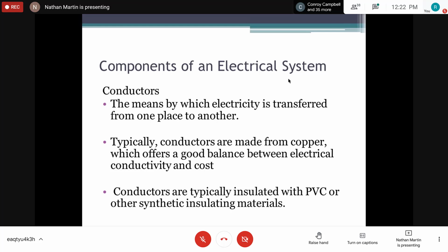Now, the different types of cables that we might use for the incoming electrical service. So remember, we talk about the entrance, we talk about within the building and so forth. We talk about the triplex wire, right? For persons who don't know, this is the typical cable used for overhead installation. So this is where you have the two black insulated conductors, and we have the bare aluminum conductor.